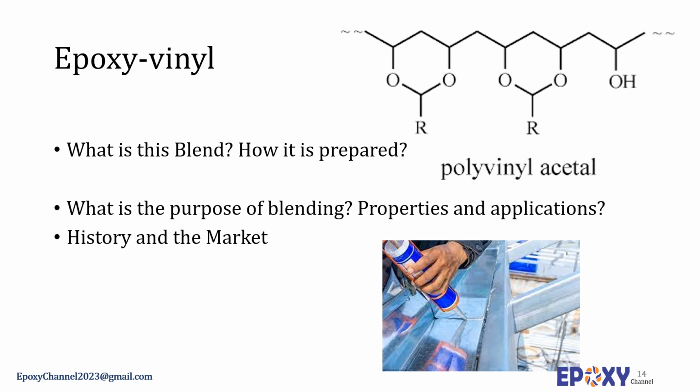Oxidation stability is excellent. Vinyl constituents increase toughness and peel strength. The adhesive is often used for bonding safety glass, aerospace engine structures, and structural panels. The addition of polyvinyl acetal improves the resulting impact resistance and peel strength of the cured adhesives. However, temperature and chemical resistance are sacrificed by the addition of low glass transition temperature vinyl resins.